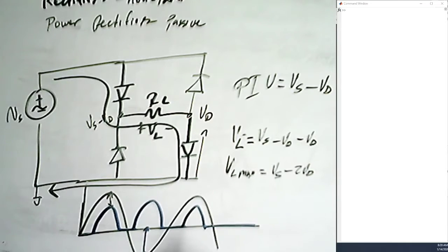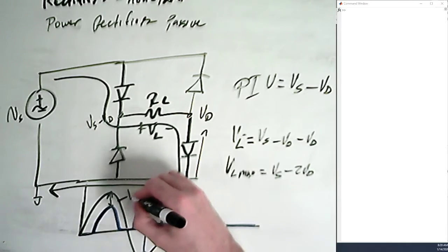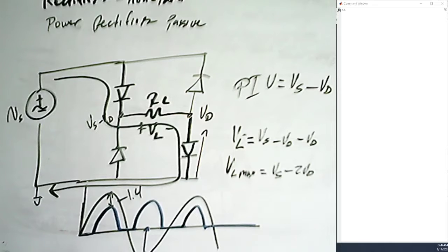We have to go through two diodes, so this is going to be a 1.4 volt drop. That's a concern because that means that we're wasting a lot of energy. Imagine that we only have a 5 volt signal going to this, and we essentially waste almost a quarter or a third of our voltage over the diodes. And so that's a significant drawback of this particular bridge setup.